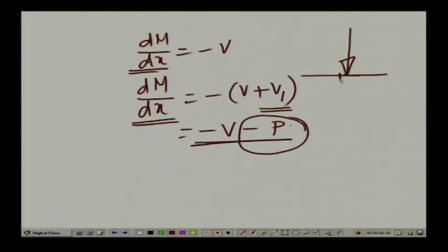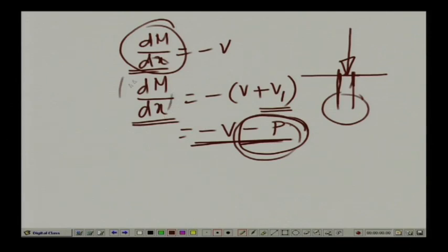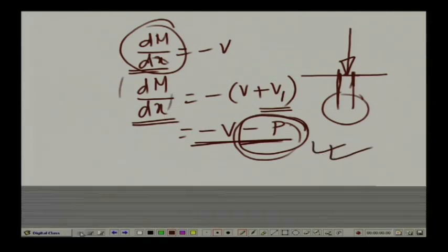On the right side there will be a difference of minus P over the dM/dx value on the left side. So, there will be a drastic change in the rate of change of the moment because of the concentrated load. So, this is an important observation.